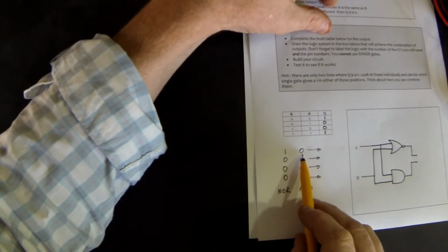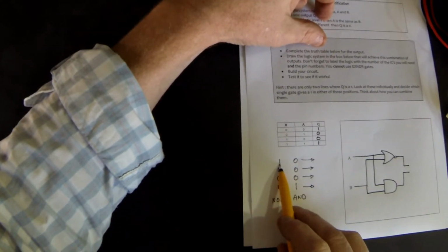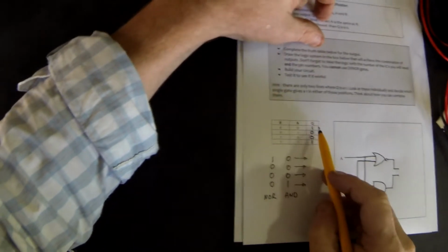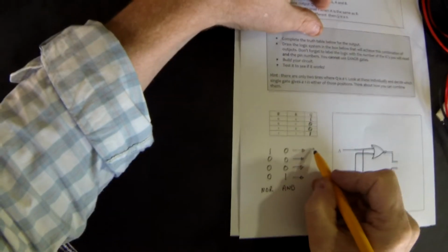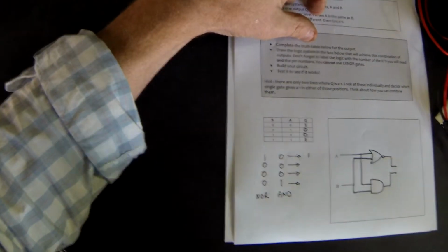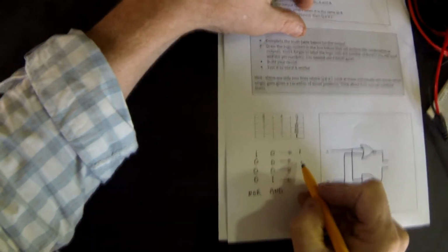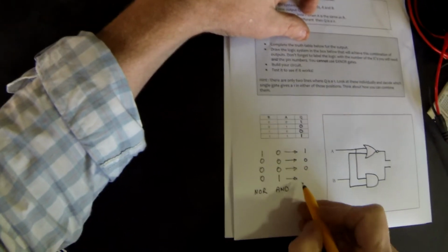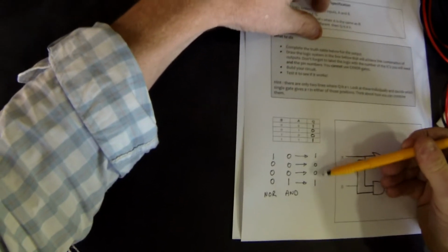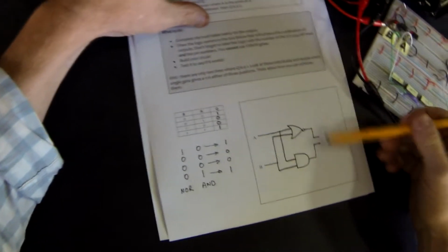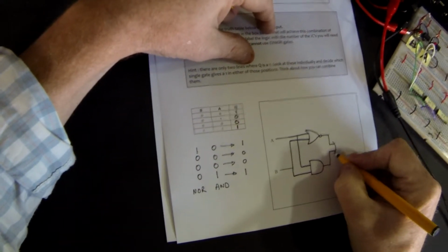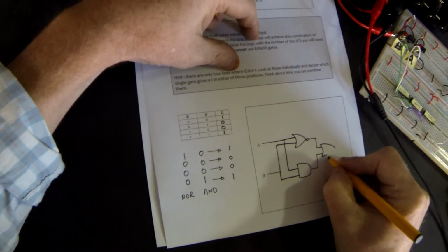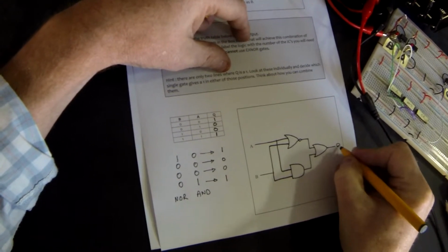Well, if we say it logically and look at it logically, if we had a 1 or a 0 here, that would give us a 1. So an OR gate would give us a 1 here. What would an OR gate give us here? Well, a 0, 0 would give us a 0. 0, 0 would give us a 0. 0 or a 1 would give us a 1. So in this case, our logic gate that we could put in between the outputs of these two is an OR gate. And that should combine to give us our single output Q.